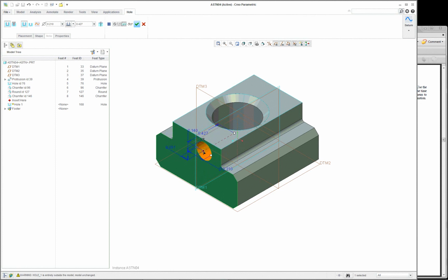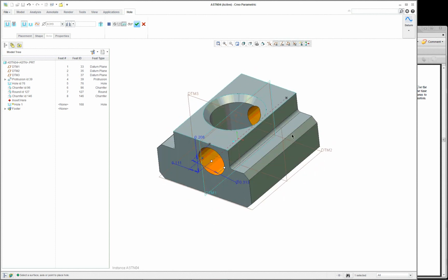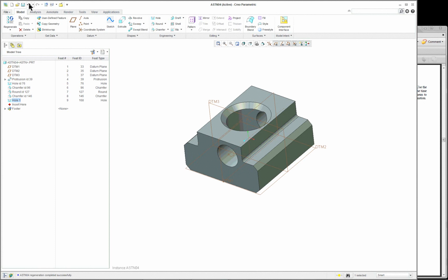as per this face by picking in the middle here. And of course the diameter for the hole. The drag handle here, drag it all the way through the model, put your cursor over the top and select through all, and that hole will go through the complete part. Check. And let's undo that. Way up in the upper left-hand corner of the quick access, and undo it. Now, that's locating a command.